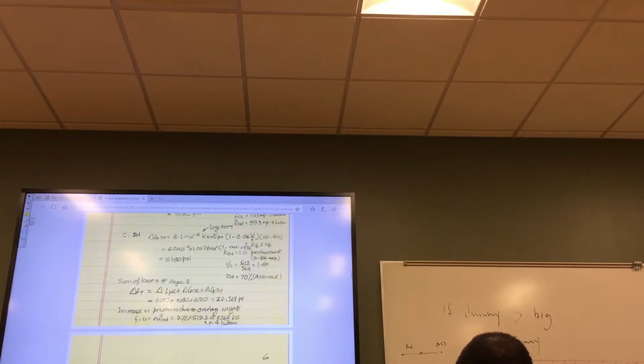Gain is right there. Increase in pre-stress due to overlay weight is the FCSD we calculated above, which is the stress in concrete due to this extra weight, or WSD or MSD, multiplied by the N, which is the ratio of the elastic moduli.